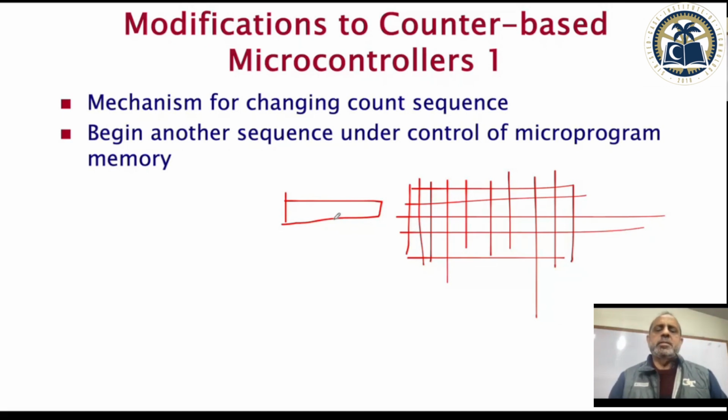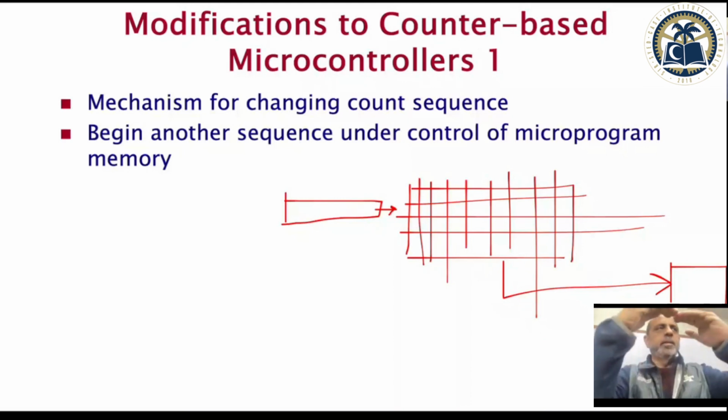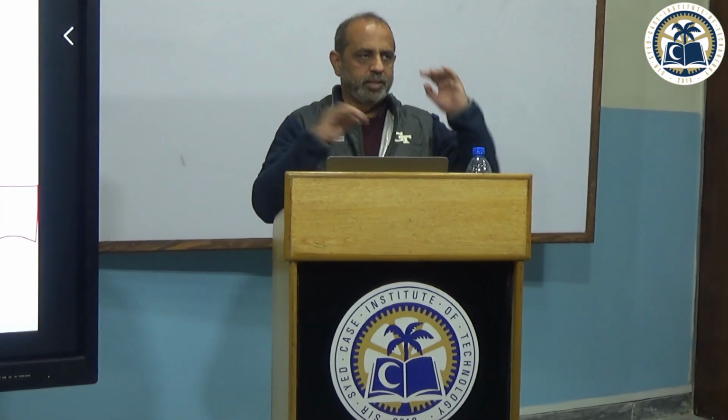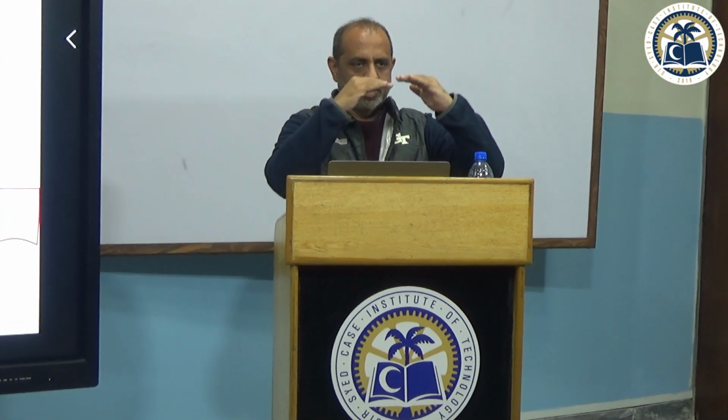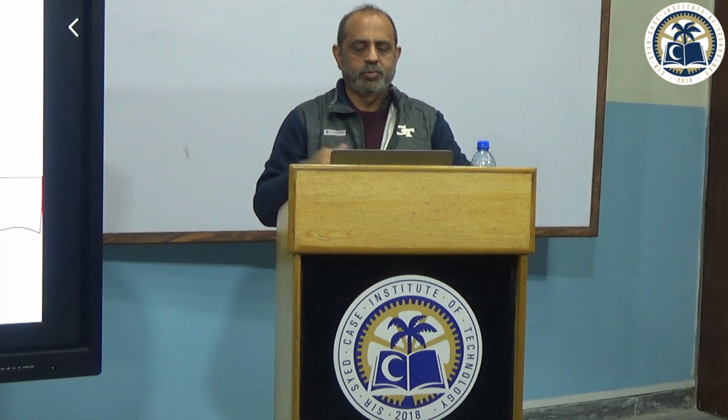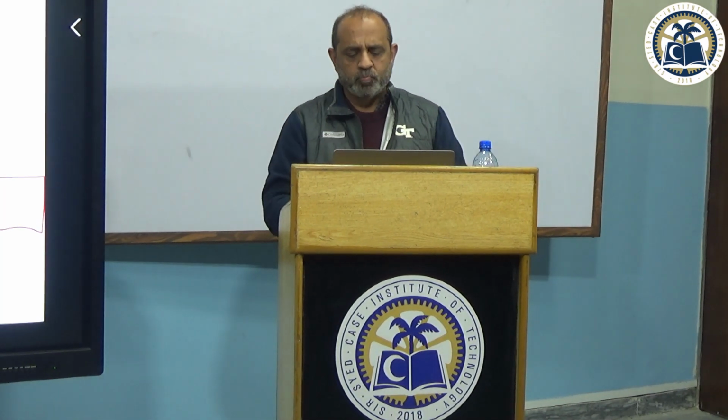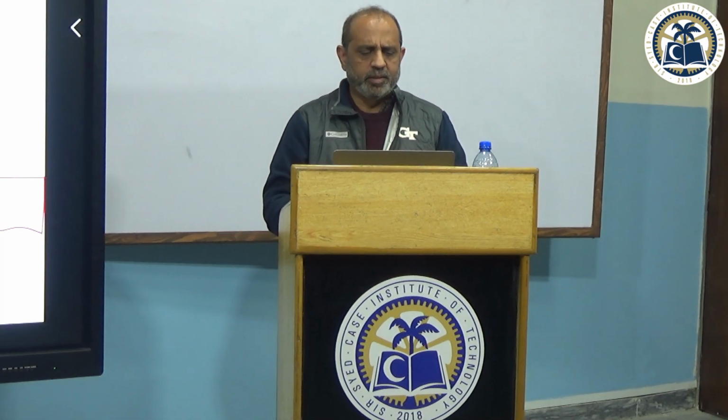So you just start this register and it will generate all these control signals, and all these control signals go directly to the data path, because they are controlling the muxes and the enable signals, and they all are stored in memory. You're not really worried about anything. This is a sequence I'm going to execute and I'm done. So this is very, very good.